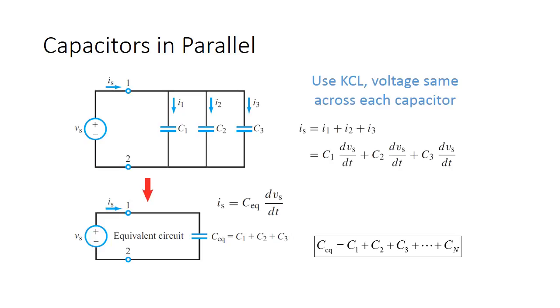And that's a really easy way to remember in the future if you ever forget which way capacitors add: capacitors in parallel add like resistors in series. So capacitors in parallel, you just add them up because it's essentially the surface areas that matter. So if the surface areas matter, 1, 2, 3, then you have 3 as your final capacitance.